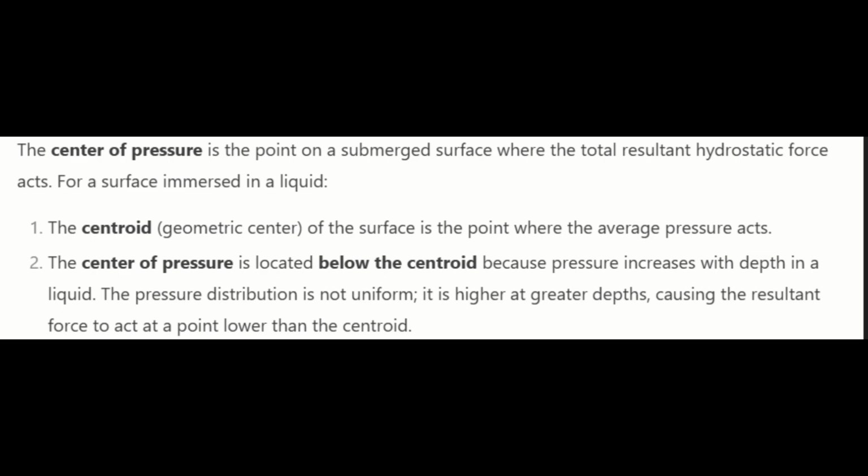So that hydrostatic force, p equals rho g h, increases with the distance. By applying simple logic, pressure is maximum at the very bottom of the surface, and for it to be maximum at the very bottom, the distance should increase. So obviously the center of pressure would be at the bottom. So center of pressure is located below the centroid.